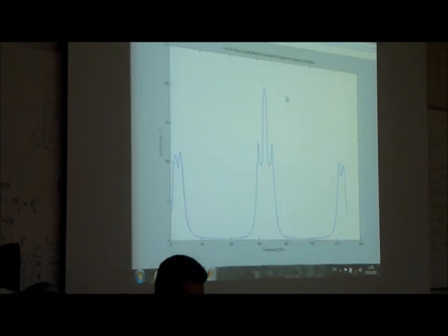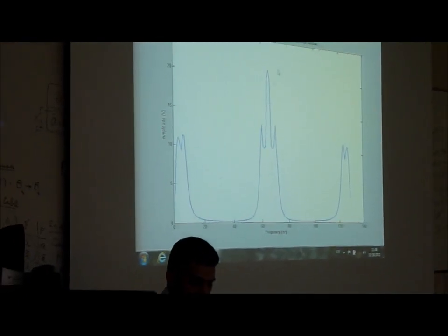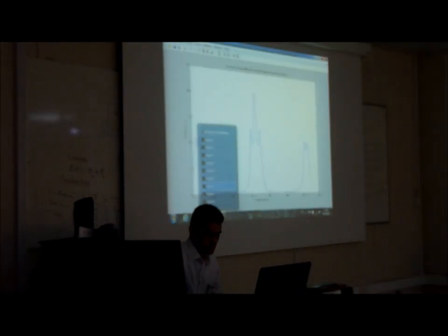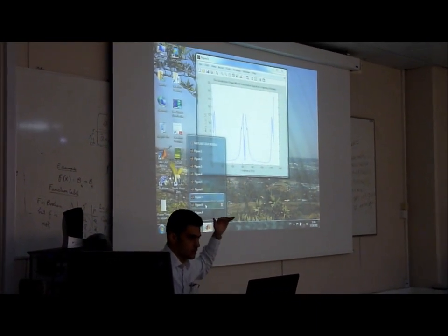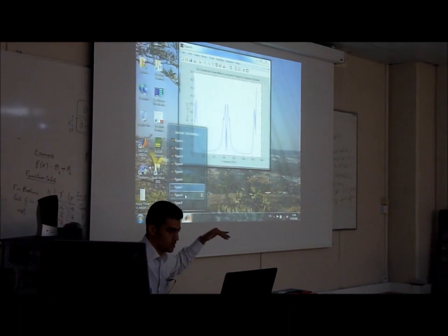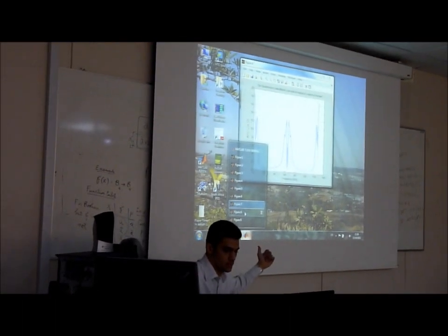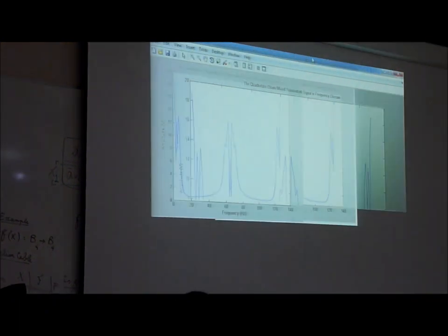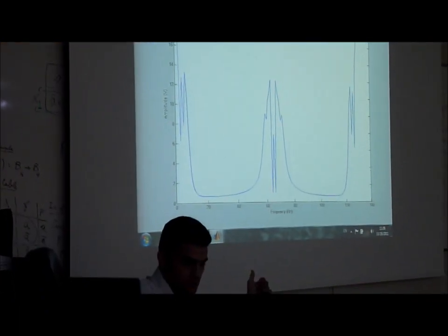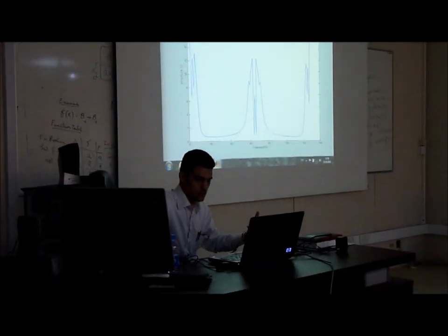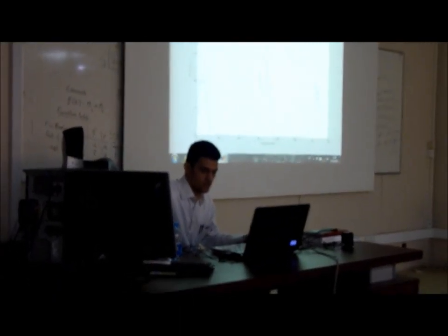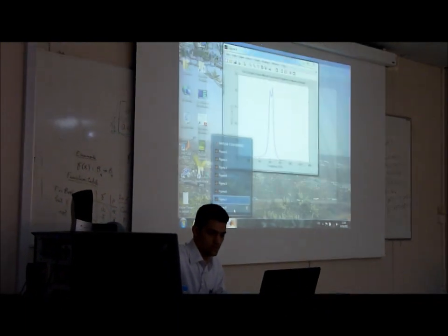This is the in-phase component of the transmitted signal in the frequency domain. And when you use the down mixing, which is the sine and cosine branch you've seen in the block diagram, you'll have the other one, which is the quadrature down mix component. And then you take the complex number of this signal, so you'll have the complex down mix signal.